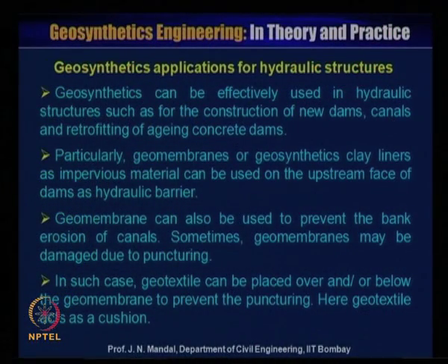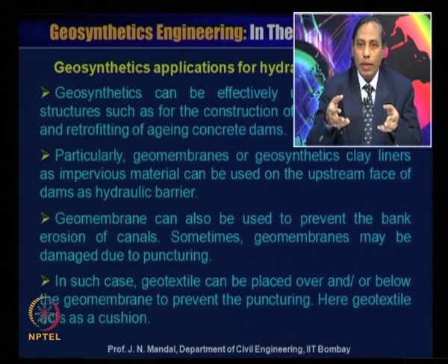Now, geosynthetics application for hydraulic structures. Geosynthetics can be effectively used in hydraulic structures, such as for the construction of new dams, canals, and retrofitting of aging concrete dams. So, you can use geosynthetic material for a new dam. You can think about a dam: a huge quantity of earth is required, and a huge quantity of concrete if it is a concrete dam. Geosynthetics can drastically reduce the volume of soil and the volume of concrete, and also if there is any problem with the existing concrete dam, you can retrofit and repair it.